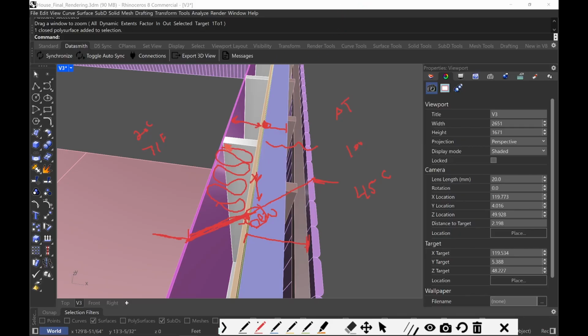Someone else might say you can actually install this insulation for sound attenuation, not to block sound, just to mitigate it. But that's really important to understand, because if you're going to start detailing a lot of wall sections, you're going to confront this a lot in the professional world: where you place your exterior insulation, and the permeability of your air barrier.